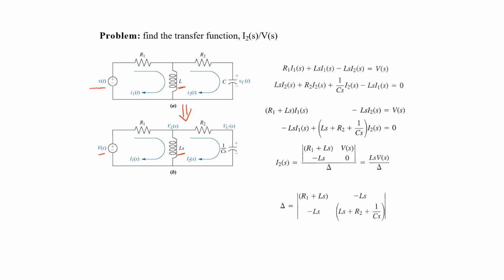So now what we will do is write an equation for each mesh. Like here, this is for the first mesh. So this equation is found by just applying the KVL on the first loop here. And when we are dealing with the first loop, we will take the sign of the I1 as positive and the sign of I2 as negative.